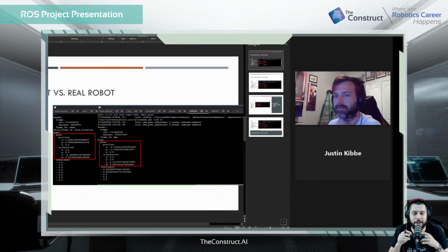You can actually move it, the X and Y, but you can't rotate it, because then the local and global costmaps won't adapt to that. So you'll have problems, because Nav2 just didn't consider that. You have to go in there and do the work yourself. But yeah, I thought that was very interesting, and I wanted to clarify that and why you should always use AMCL pose when you start up navigation.